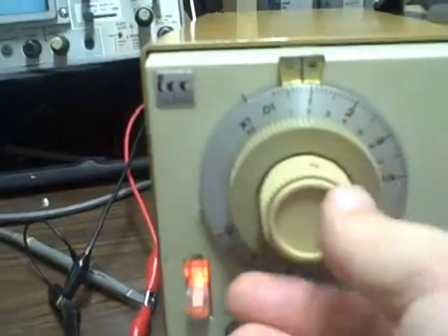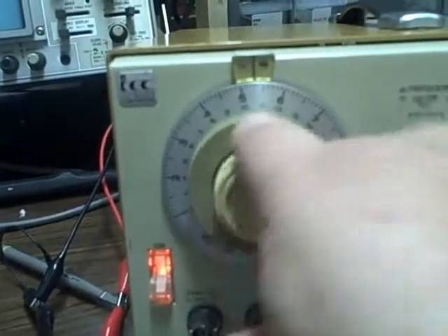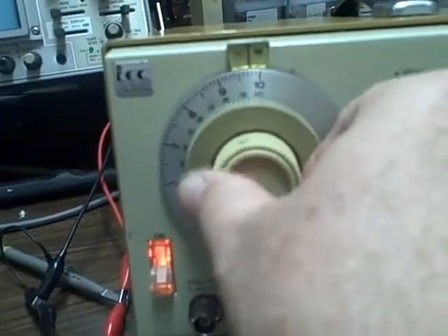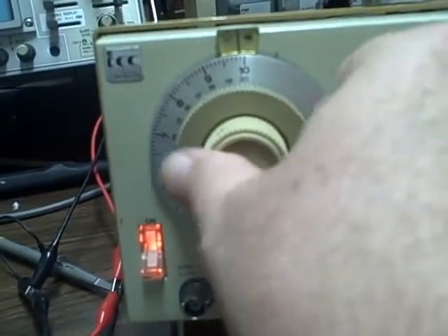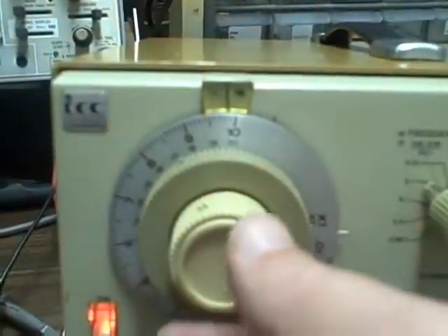We're getting our sinusoidal graph on the oscilloscope, and then I'll start to rotate, take us to the other end of the range. Alright, we should be somewhere around 10 hertz up in here. We definitely have picked up a sinusoidal trace. We're at 10.6 hertz right now, and I'm at about 10 on the scale.